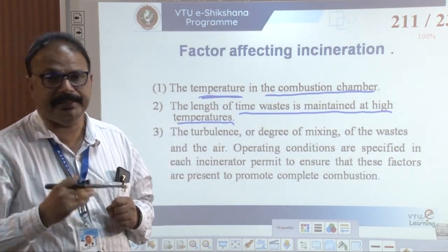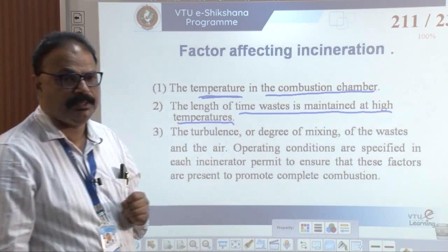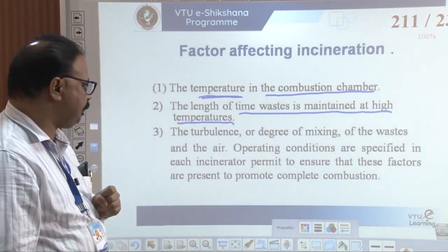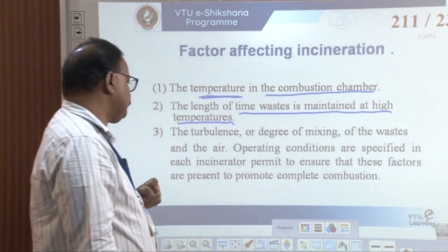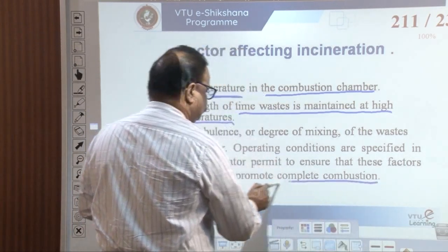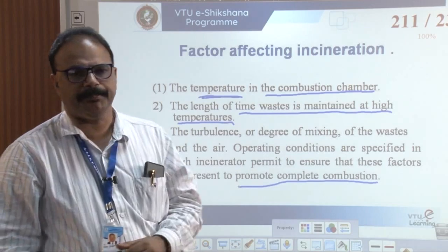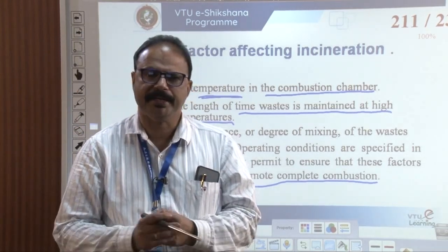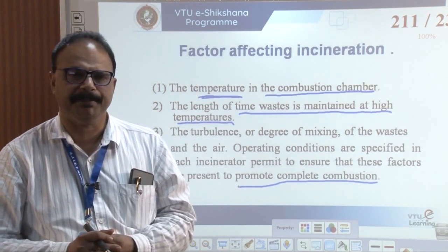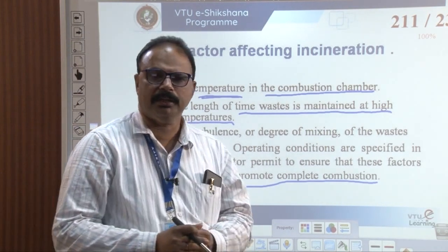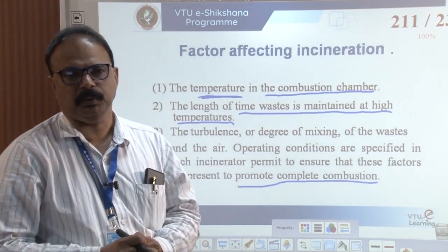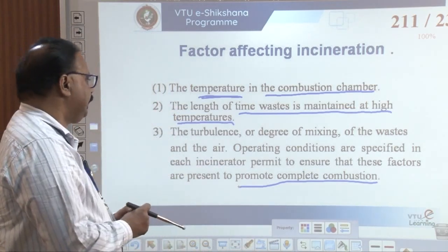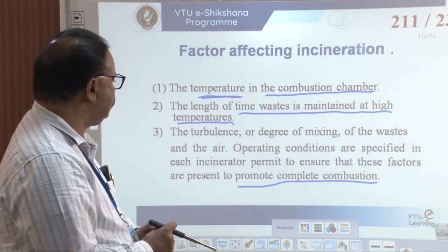And the turbulence, the degree of mixing of the waste and the air. Operating conditions are specified in each incinerator permit to ensure the factors are present to promote complete combustion. These are the three factors affecting. First one is the temperature of the combustion chamber. Length of time waste is maintained at the high temperature.